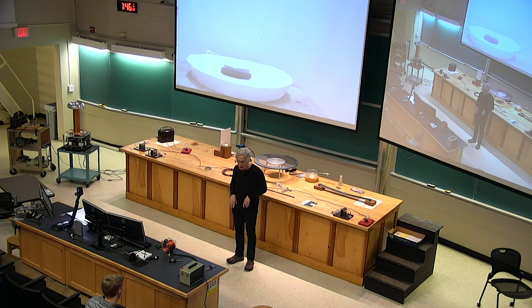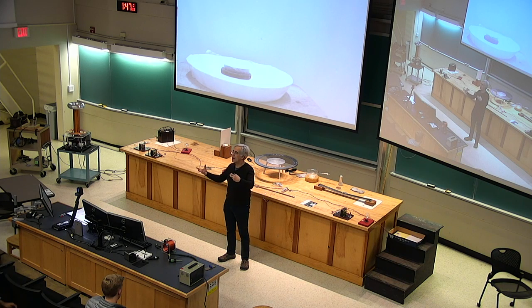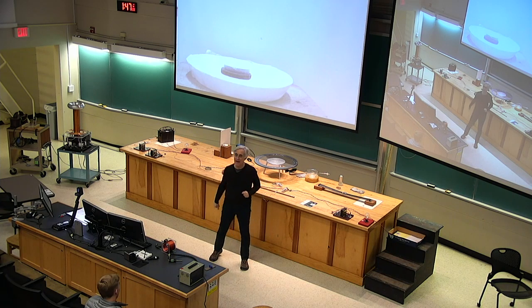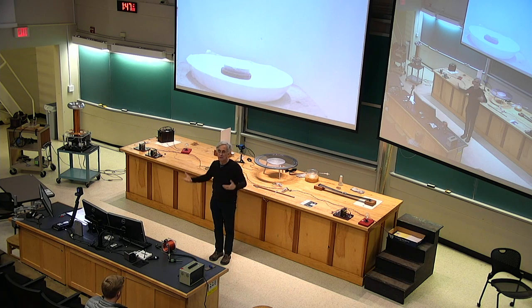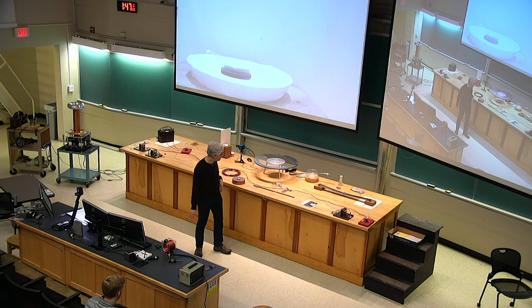How do you make a motor? To make a motor, use an electromagnet to attract another magnet, maybe a permanent magnet, and just as the permanent magnet gets lined up with the electromagnet, change the electromagnet, reverse its poles. So just as the north pole of this permanent magnet gets close to the south pole of the electromagnet, switch them, so that now the north pole is near a north pole. It repels, and it continues. And you basically chase the permanent magnet around in a circle with electromagnets. Or you can chase an electromagnet around in a circle with permanent magnets, various choices.